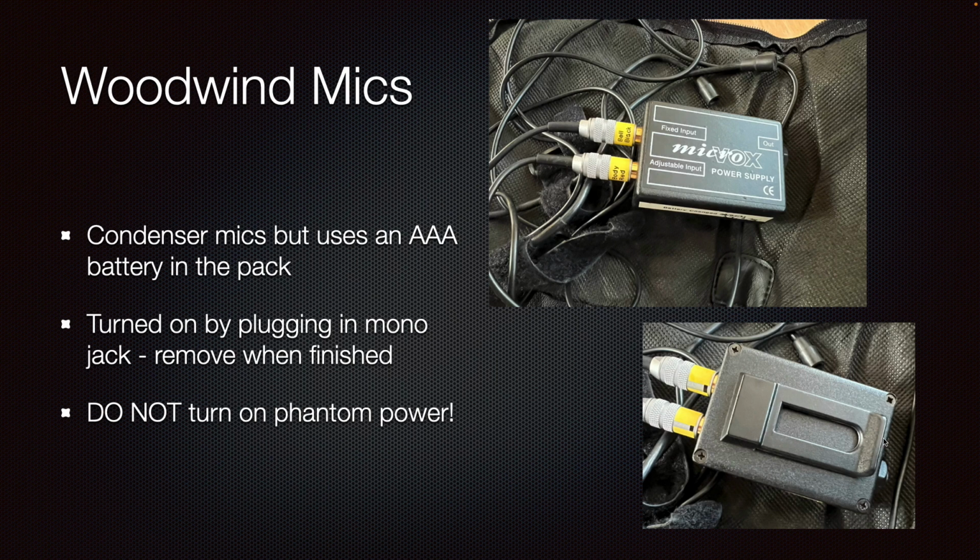So you turn it over, undo the 4 screws, and you'll see the AAA battery inside. Under no circumstances put phantom power into these microphones. They really won't like it. So that's just one about our woodwind mics. So that's microphones. What about guitars?